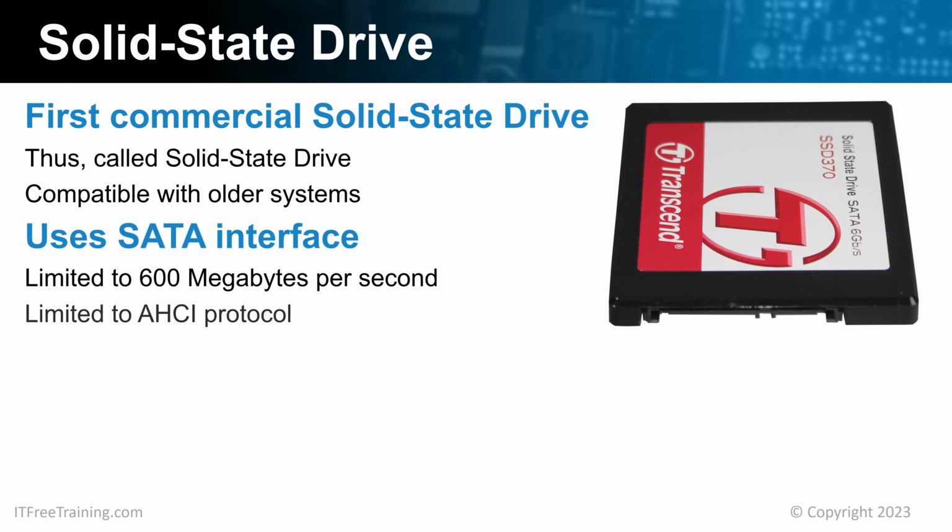The next problem is that SATA uses the AHCI protocol. AHCI, or Advanced Host Controller Interface, was designed more with hard disks in mind rather than solid-state drives. For this reason, it is not as efficient for solid-state drives.